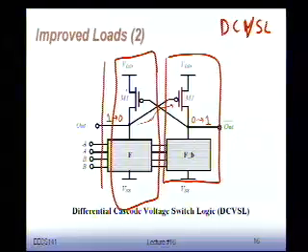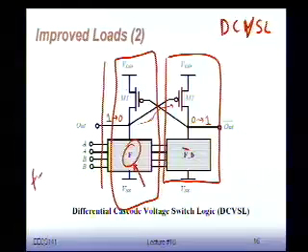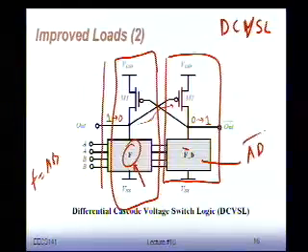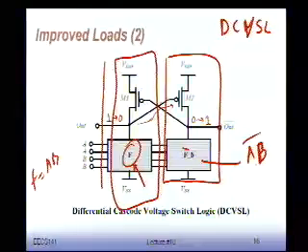Okay? The other thing to remember is that this is F. This network is the complementary network. So if this network F implements AB, the other network we're going to implement AB bar. So they're basically complementary to each other, and I'll show you examples of how this exactly works. But remember, I always have A and A bar available. That's going to help me a lot with this complementary type of network. Both of them are NMOS networks.